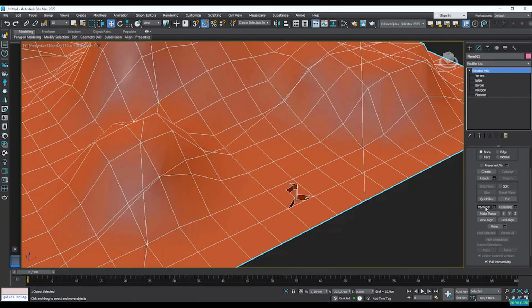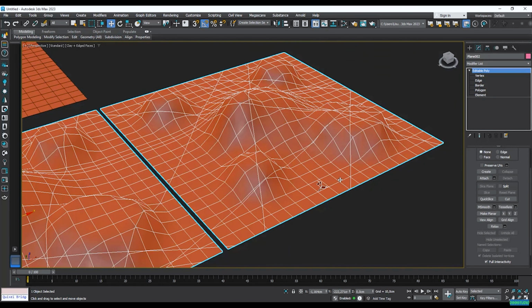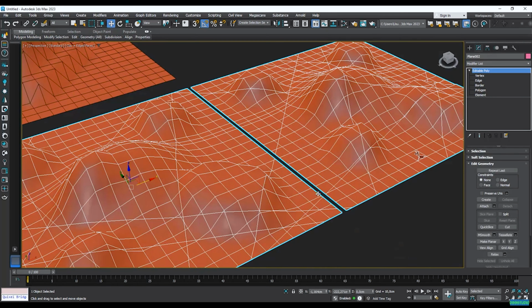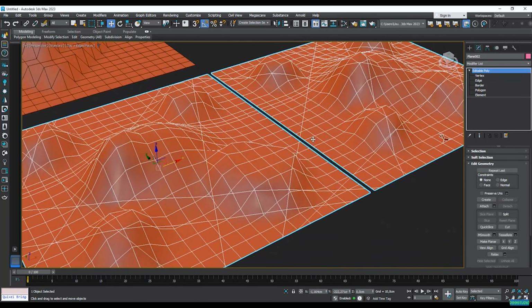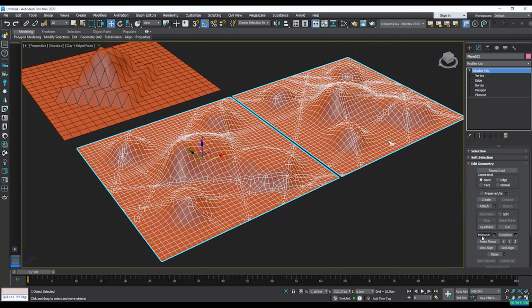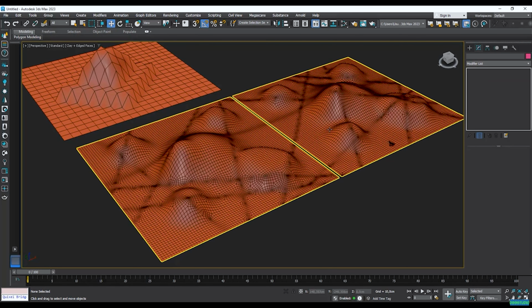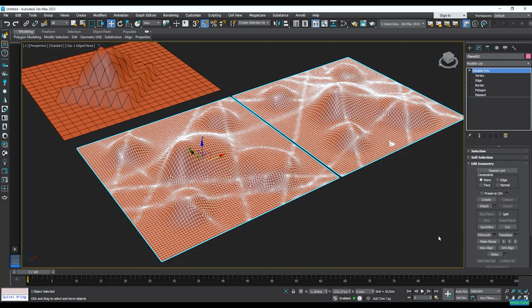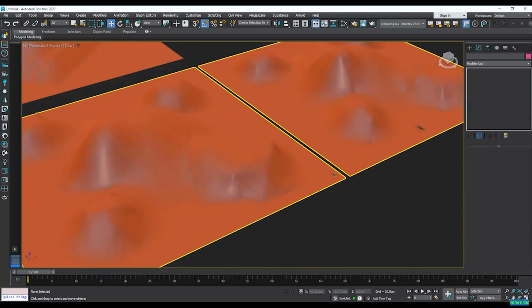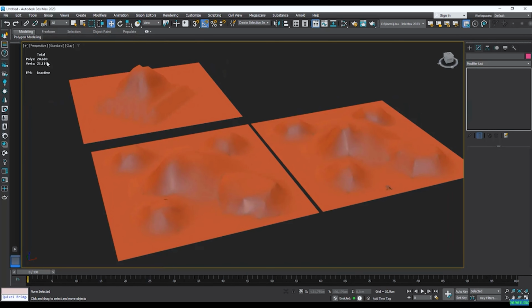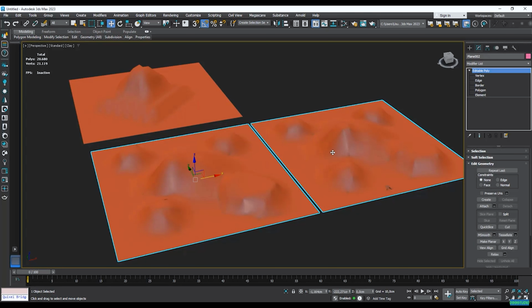I now have the mesh smooth. Okay, so what mesh smooth will basically do is just multiply the polygons that are creating this mesh. So if I click once, you can see that now they've multiplied. And then if I click again, they'll just soften up my surface. Just like a turbo smooth, for instance. Okay, let's press F4, but we have to be careful of how many mesh smooth we apply to this geometry